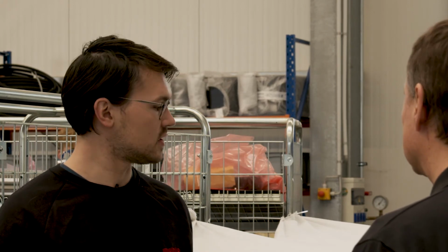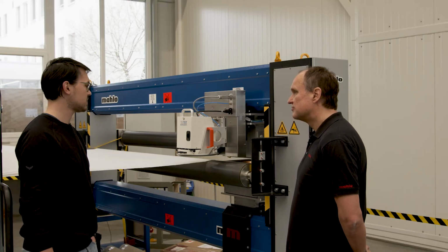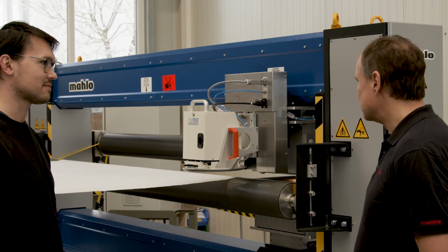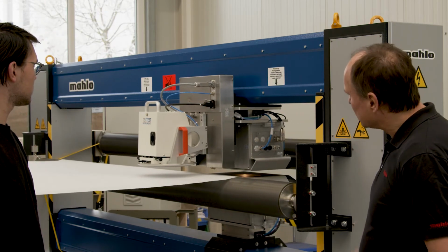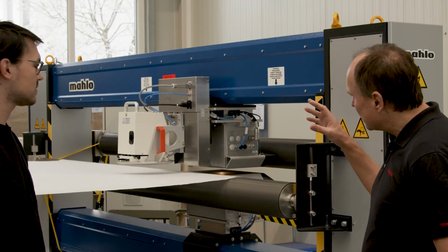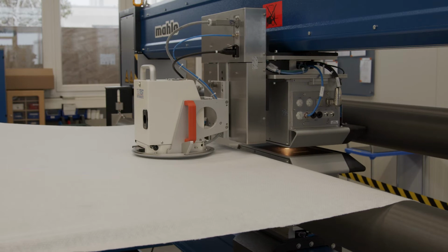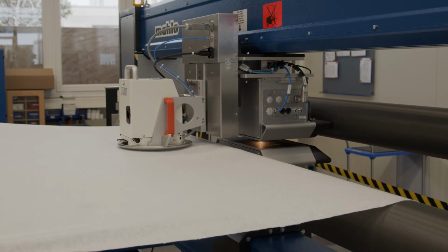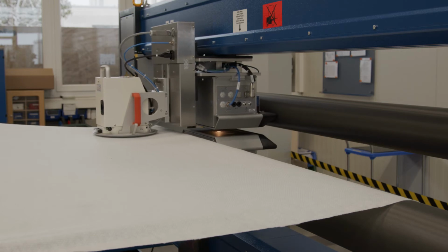of the product. In this case we use a Nonwoven product for our test, and I think we start, and then you can take a look by yourself. Of course, happy to do so. So now it's starting, and the air permeability sensor is above the web. Now it goes down on the web and starts the measuring process, right?